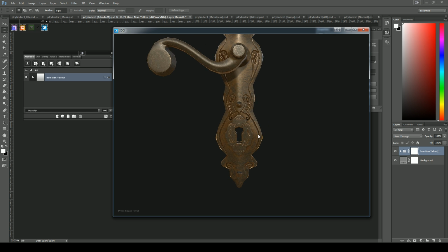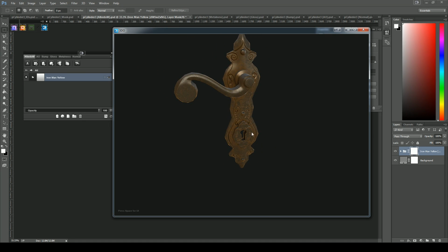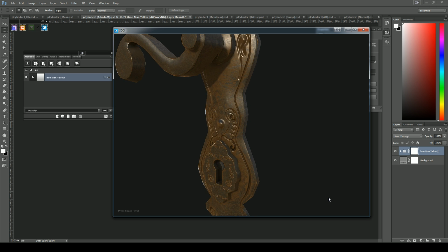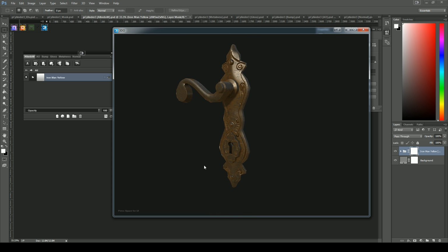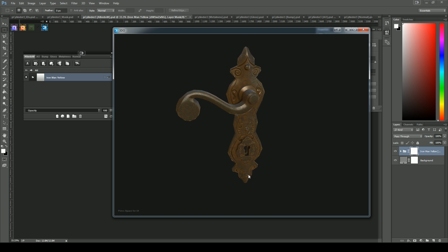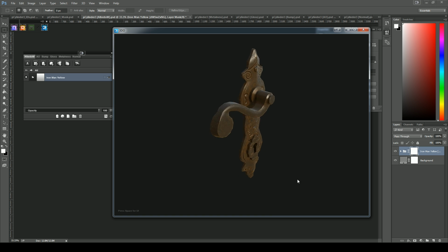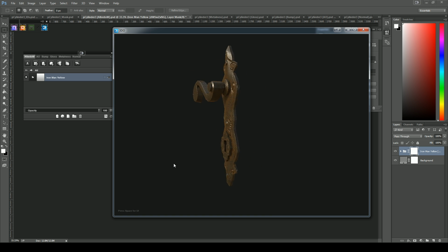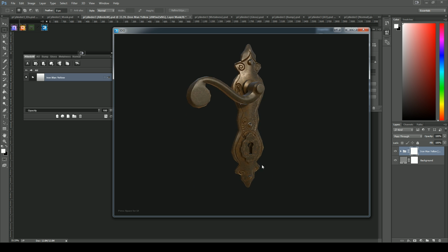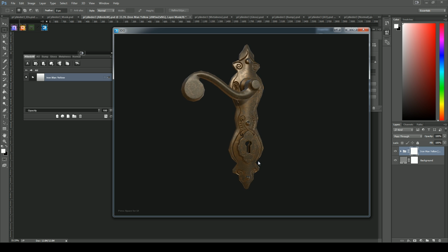This video series covered a range of production workflows. So bringing something into Mudbox for subdivision. You've seen how subdivision modeling works in that you have to work with quads the whole time. So you can't smooth N-gons or triangles even will pinch a little bit. You've seen the workflow of sculpting detail through Mudbox and then exporting out a high poly model.